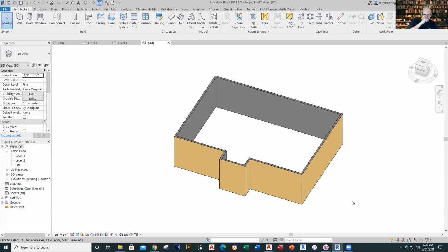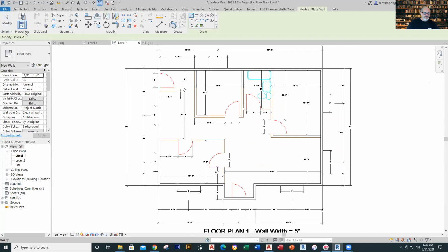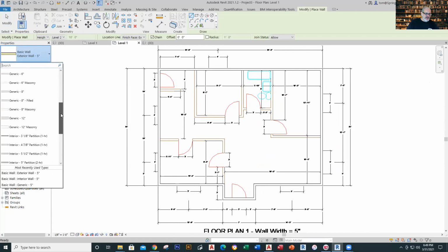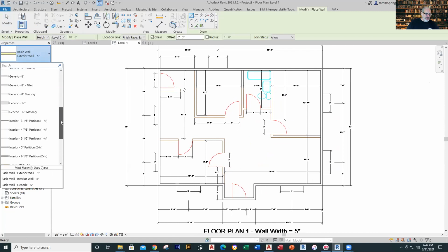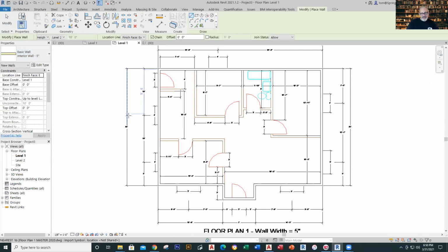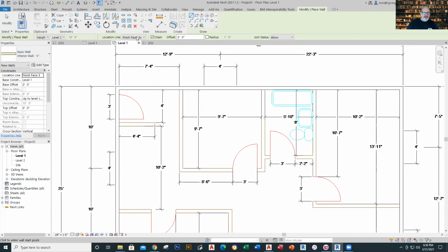That's your basic shell. Now the other thing you would do is switch to your interior wall. So you go to wall, and you go to wall architectural, and you can guess what I'm going to do now. I'm going to go down to wall interior. Interior wall, down here. Yeah, it's called interior wall 5-inch. Mine have that kind of character to them, so I've got that. So what I've got right now, I'm going to change this from finished base exterior to wall centerline because it's a little bit easier to work with here.